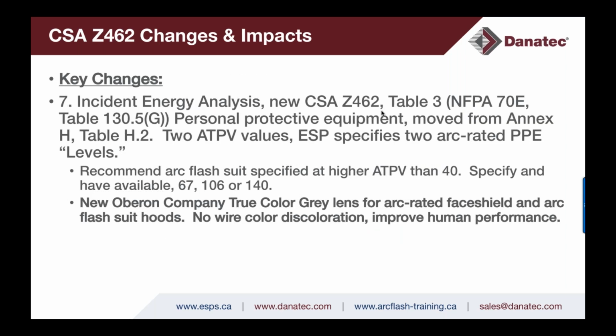So I mentioned this earlier. No, I didn't. This is actually something different. What also happened, and it relates to this confusion on selecting arc flash PPE, is that we had incident energy analysis studies being completed, and the reports came out listing an HRC number, and it never should have. That was a technical error related to the engineer that completed those studies, because they never should have correlated HRCs to incident energy, because IEEE 1584 doesn't do that, and neither does 70E or Z462. So this was a change that was trying to fix this problem.